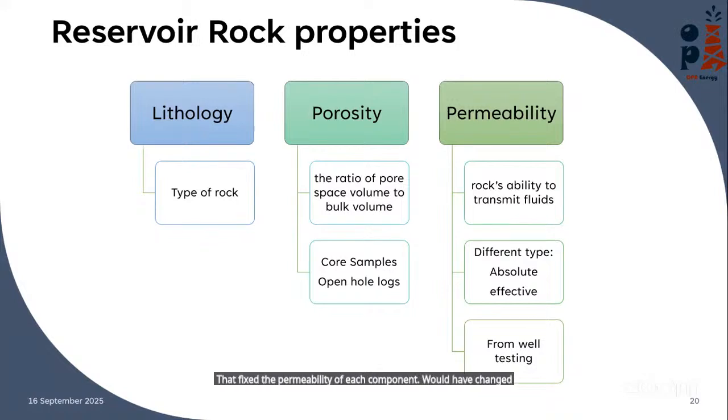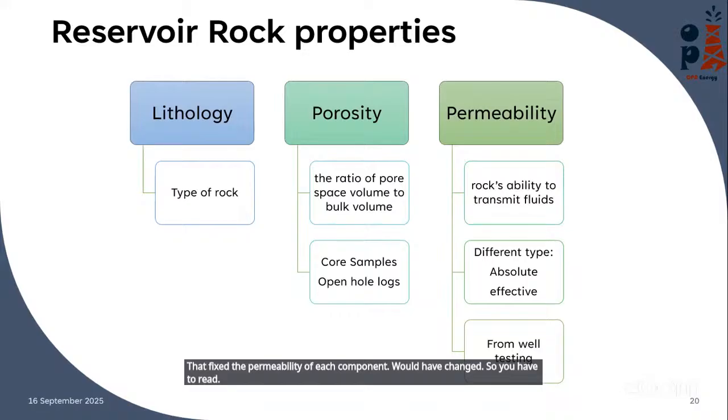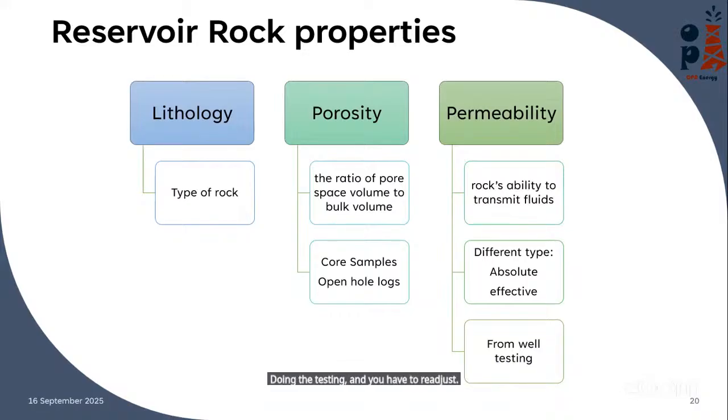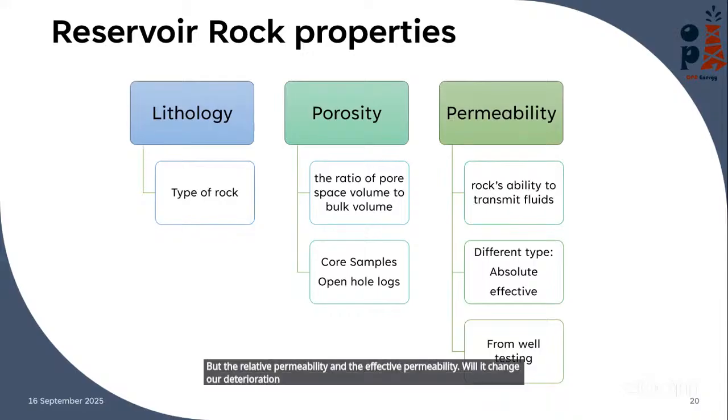So you have to redo the testing and readjust your calculation every time. The absolute permeability of the rock, if you don't do any stimulation, will be constant. But the relative permeability and the effective permeability will change as the saturation of each component changes.